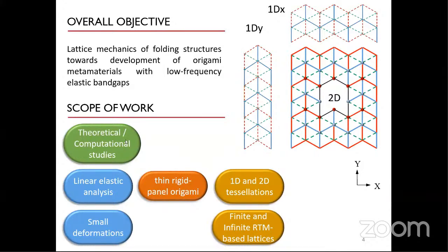So we plan to conduct theoretical and computational study focusing on linear elastic analysis of thin rigid panel origami within small deformation limits. We will look at both 1D and 2D tessellations as shown here, and we will draw insights from both finite and infinite lattices of rigid triangulated Miura-ori.